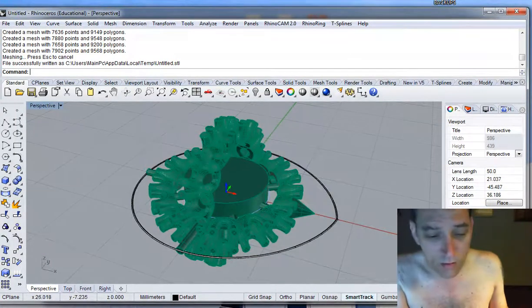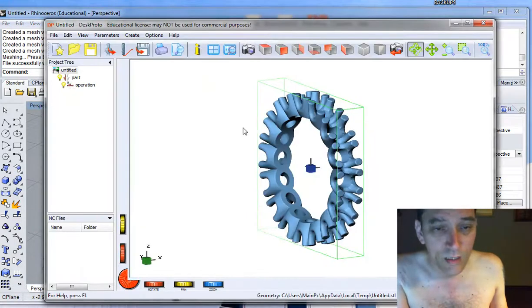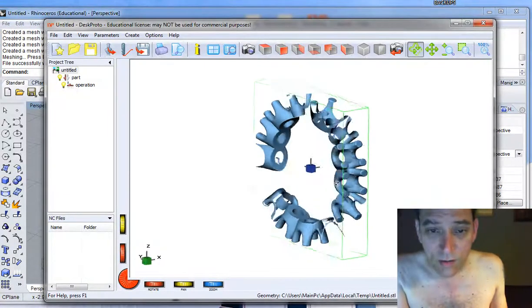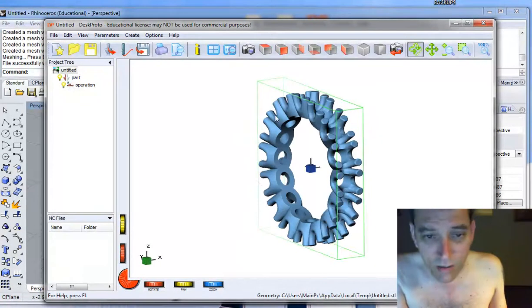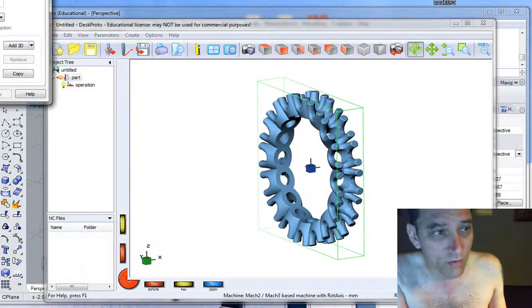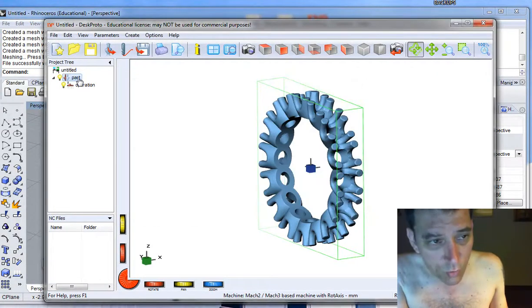Okay, so what I'm after is what happens when you open this. It opens, it's fine, alright, but your defaults have not been applied. It thinks that it's trying to cut an index. If I look at it over here, it's trying to cut an index. It's not even using the rotary axis. In other words, all the parameters required to do a rotary cut over here are missing.